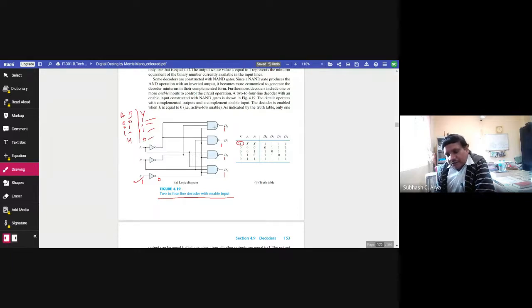In simple logic, we used to say that wherever f is equal to 1, you have information. Now, if we are implementing with the help of NAND gates, we say that wherever the logic is 0, f is equal to 0, at that time you have information. Okay, that gives reverse logic. So please keep it in mind.